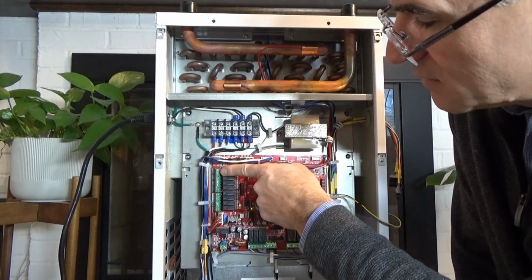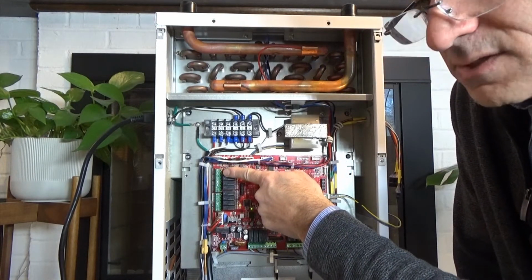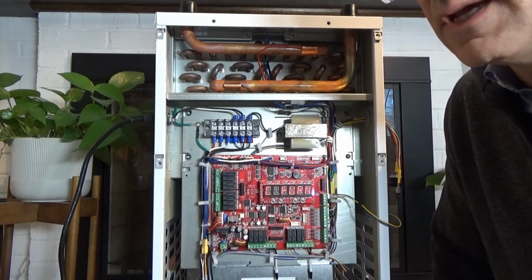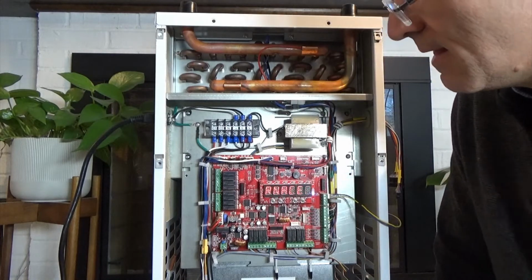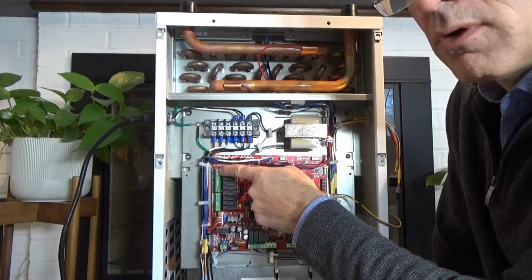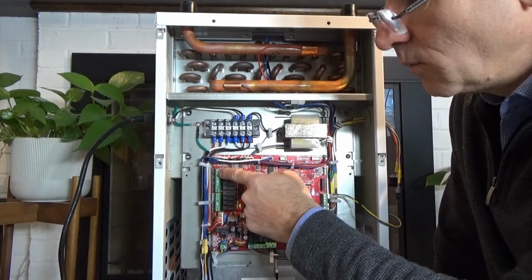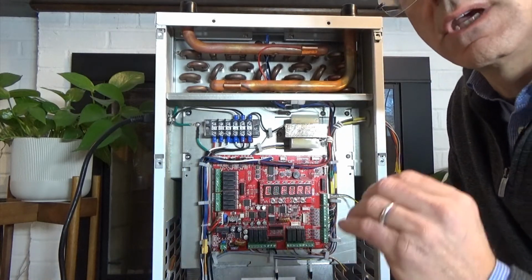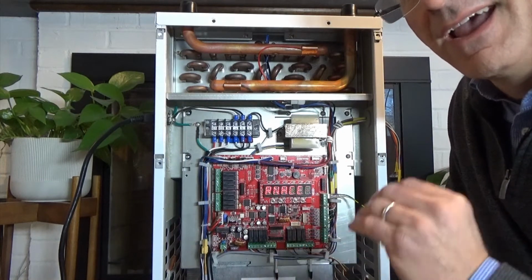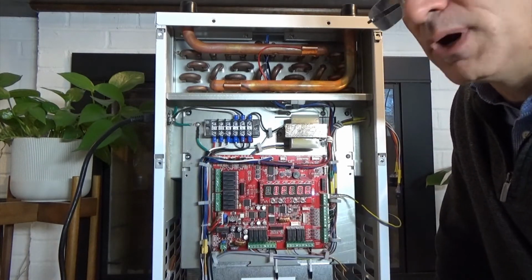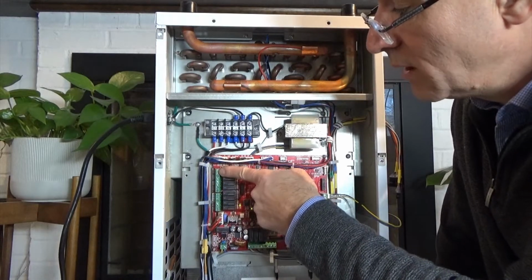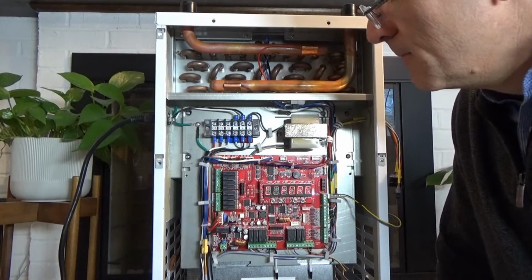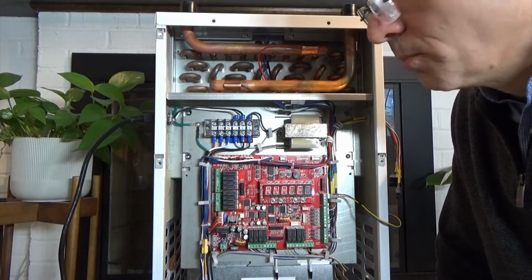The top is the circulator. Now that circulator is not the variable speed circulator that we would use to bring the water into the iFLOW. This would be a 24 volt output on a heating call that would typically be wired to a relay that will bring on your primary loop. So if you're using a boiler with a primary, secondary, and you need a signal to bring on your primary pump, that is where we would take the 24 volt signal to a relay and then power your primary loop pump.